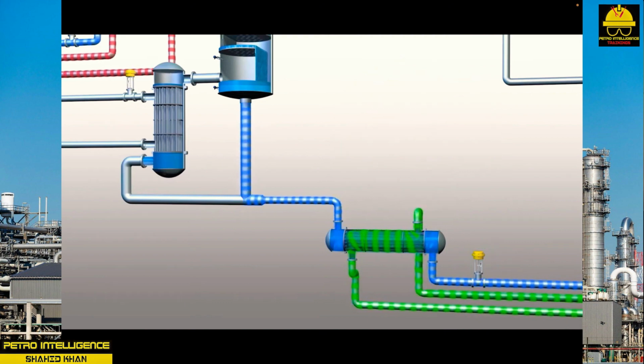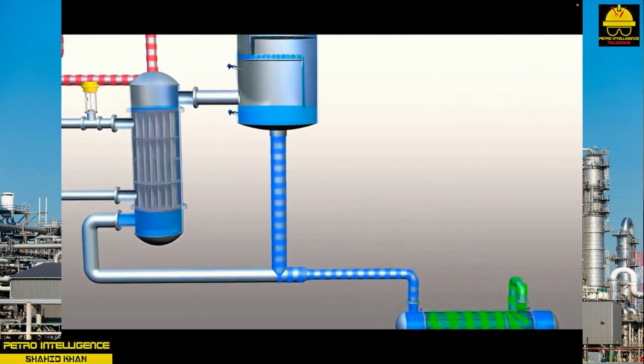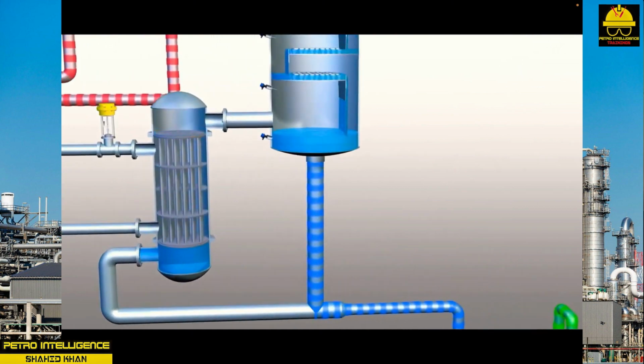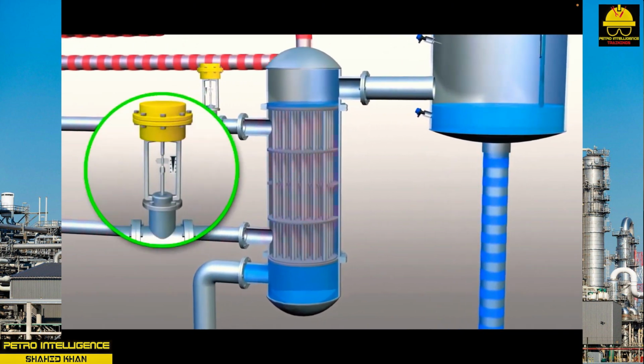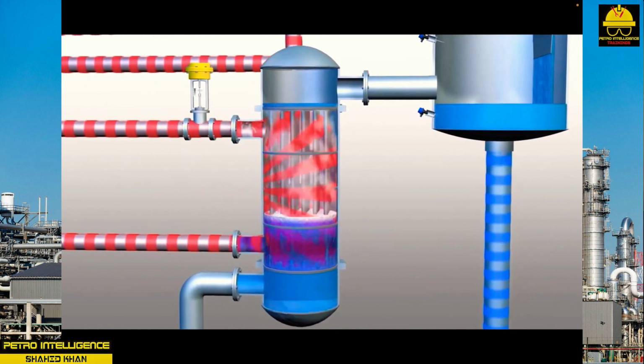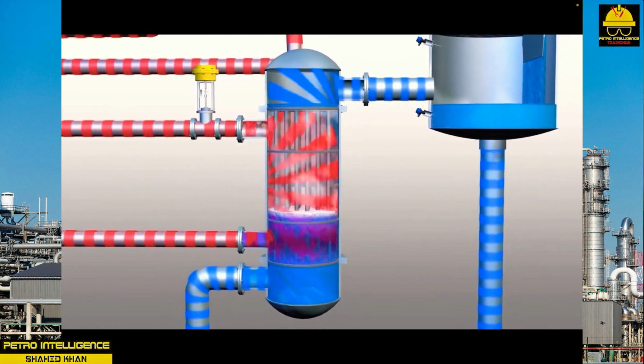Feed rates into and out of this system are carefully controlled. The distillation column can be a pack or plate type column. Plate columns have a series of trays stacked on top of each other. Packed columns are filled with packing material to enhance vapor-liquid contact.